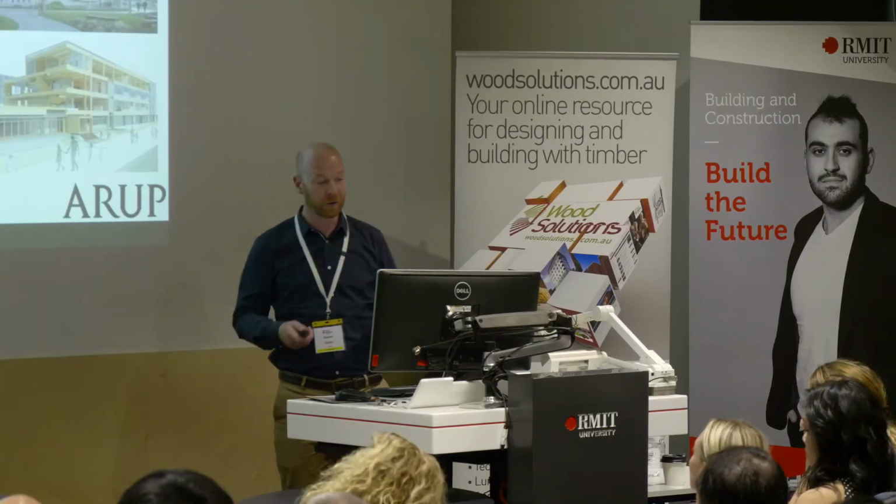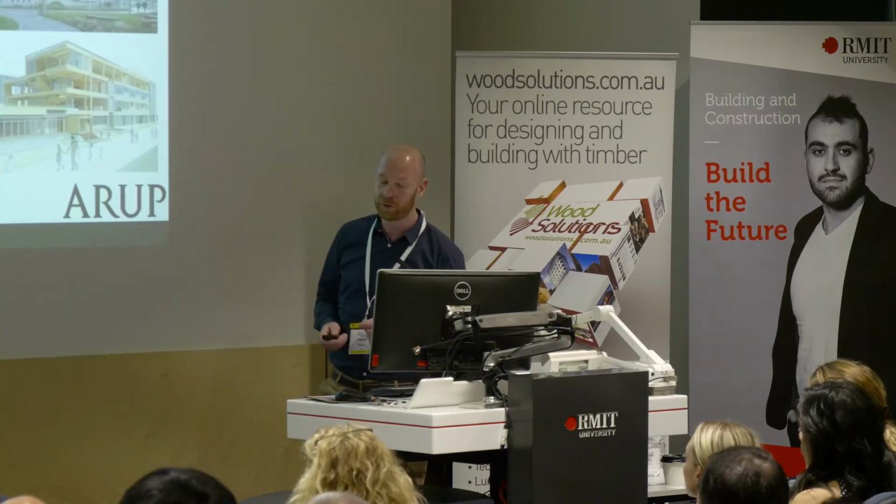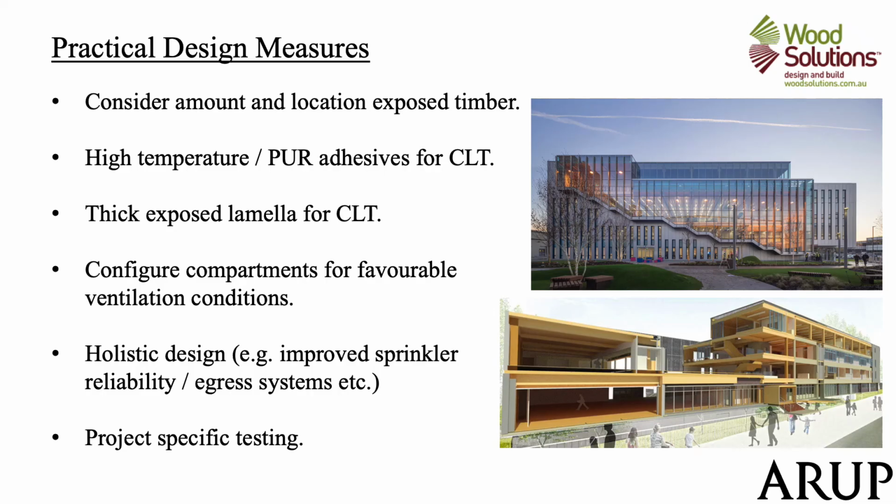So this is WoodSolutions, so a couple of practical design measures, some solutions. We should definitely consider the amount and location of exposed timber, particularly in the context of the risk of the building. If it's a really tall building, or a high risk building for whatever reason, for egress or whatever, then very carefully consider the amount and location. We want to really avoid large exposed surfaces of CLT. Our modelling and some of the larger fire tests have shown that you get a slightly different flashover mechanism when you've got exposed surfaces, where you get a localised flashover way ahead of the fire, and that can accelerate fire spread within the compartment.